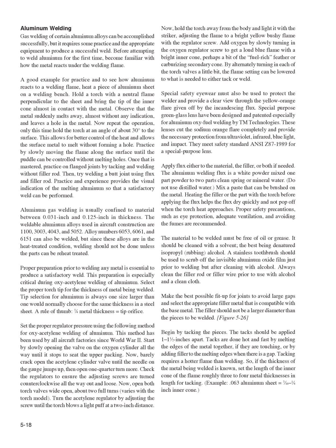Special safety eyewear must also be used to protect the welder and provide a clear view through the yellow-orange flare given off by the incandescing flux. Special purpose green glass lenses have been designed and patented especially for aluminum oxy-fuel welding by TM Technologies. These lenses cut the sodium orange flare completely and provide the necessary protection from ultraviolet, infrared, blue light and impact. They meet safety standard ANSI Z87 1989 for a special purpose lens.